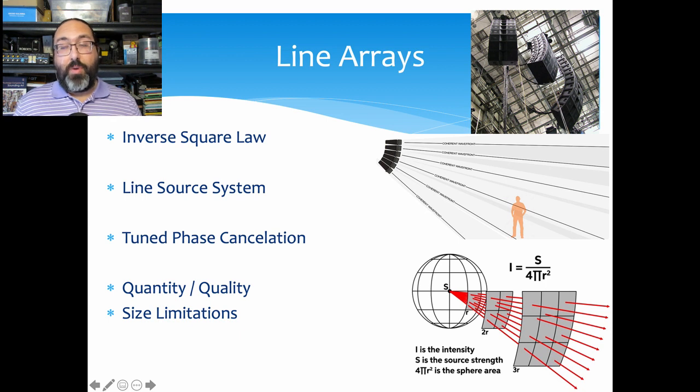That being said, you have your Meyer, you have your D&B, you have your L Acoustics. They are really, really excellent and they know what they do, but you're also looking at a 15 to 20 foot line array. There are places, and especially if you're in a smaller space, that you might want to think about foregoing the line array and just using regular trapezoidal speakers. You can do well with regular trapezoidal speakers as opposed to line array, especially if you're in a room of, say, 50. Now, if you're in a room of 50,000, you definitely want to use a line array.